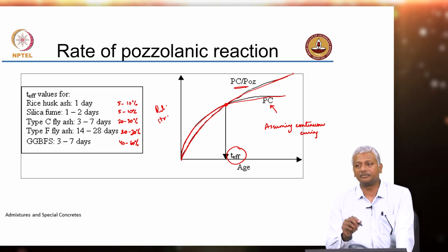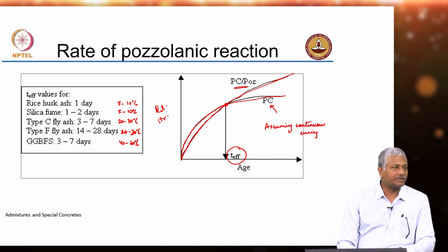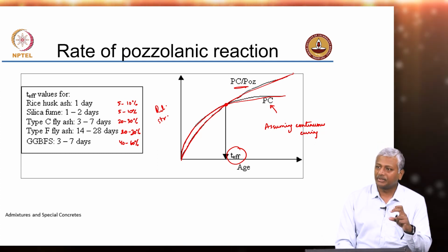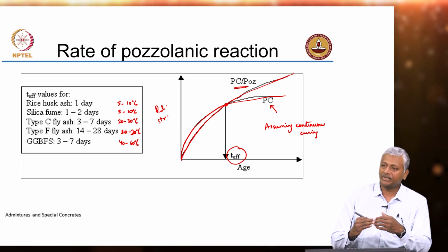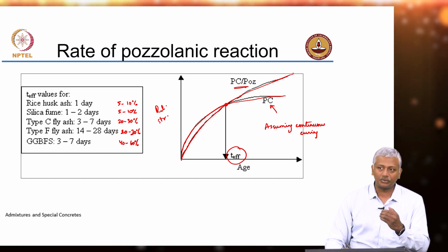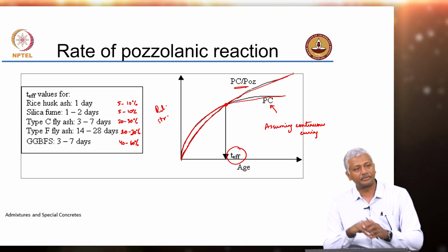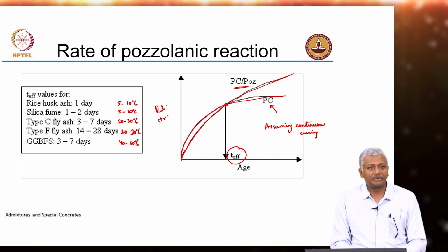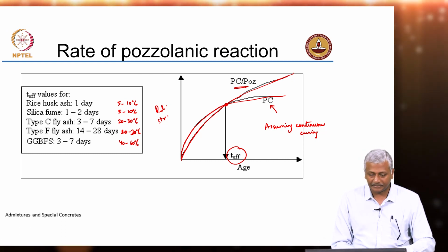The issue with mineral additives is that, because this speed of reaction gets affected, you have to have a compensation by additional curing. But the amount of time and resources that you put in to do that additional curing will significantly enhance your long term service life, and that is where you need to put all your bets, to ensure that you get a long term performance from your concrete rather than worrying about extending some periods of working in the short term. So, that is very important for us to understand.